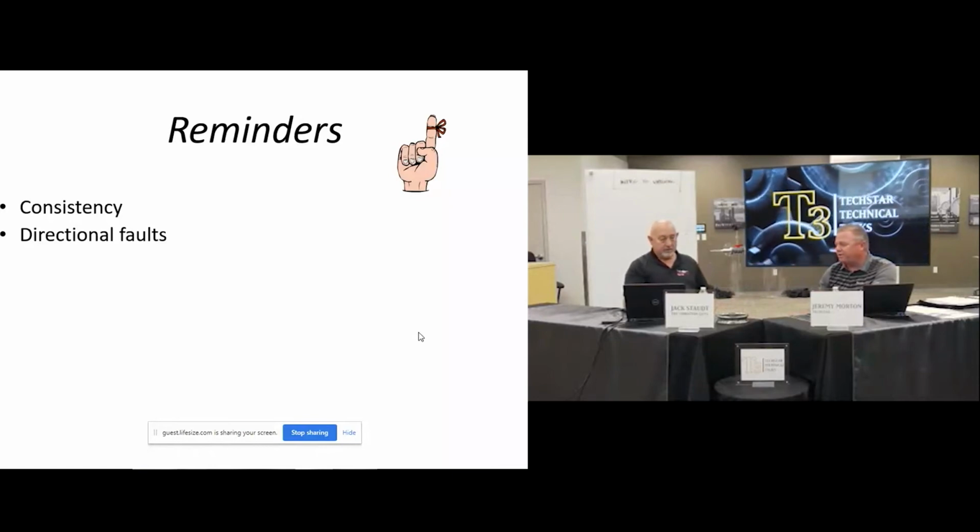Makes sense. I would say if you're connecting the system to a protection system, a trip off line, you probably want a single axis sensor in each plane, physically taking that measurement in that plane. If you're just pulling data to look at for analysis like we're discussing right now, a triaxial probably gives you the majority of the information you need. Yeah, a lot of your wireless systems are triaxial.